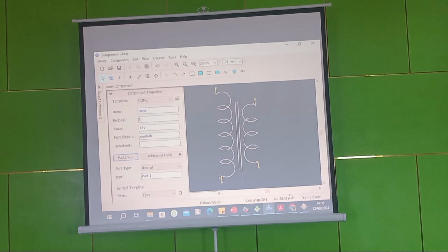When you have a 5 volt power supply, the first stage is the source. After the source, you step it down. After stepping it down, rectification. After rectifying, filter.